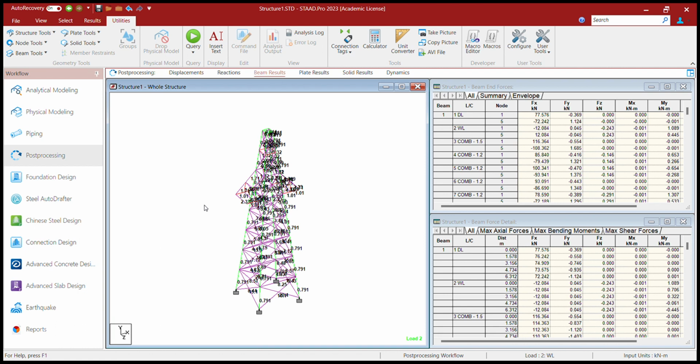Okay, for example, we'll click on this member 137. So it is pass, member 137. For the critical load case number 1, its location is given, and slenderness ratio, that is whether it is a tension member or compression member. Similarly, for all members it is given here. Okay, when you generate a report, there it will give you the total summary from member 1 to the last member, member number 160.